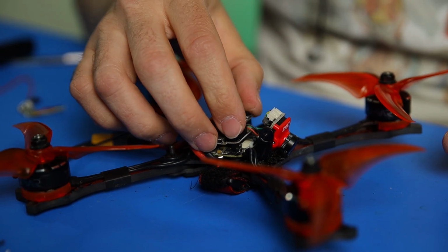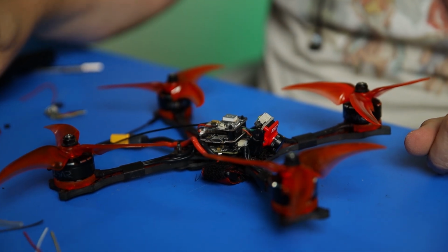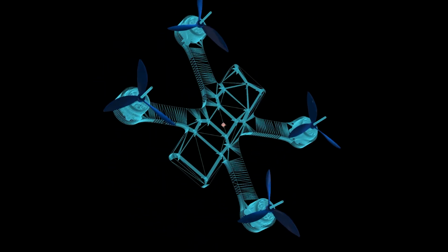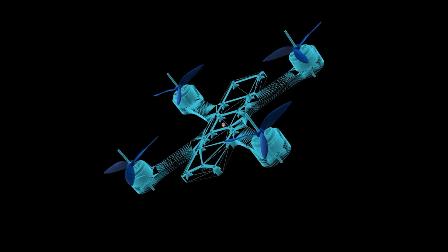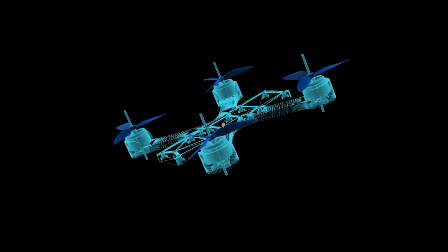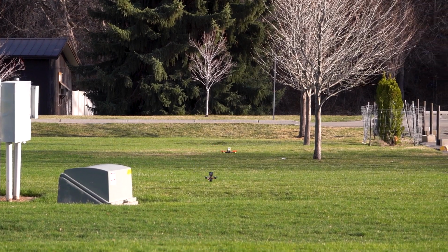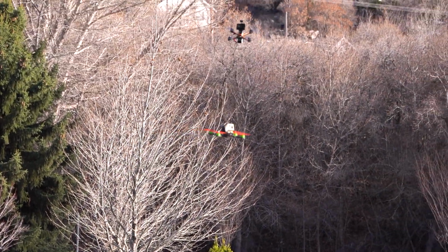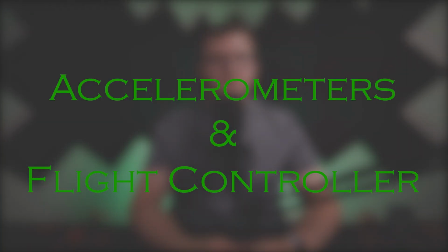gyro for short. A gyro is a microchip that records the speed at which a quadcopter rotates in each axis. Using this data and program mathematics, the flight controller can estimate the distance a quadcopter has rotated and whether its rotation is accelerating or decelerating. A gyroscope is required for the quadcopter to fly in acrobatic mode since the drone does not self-level in this mode.